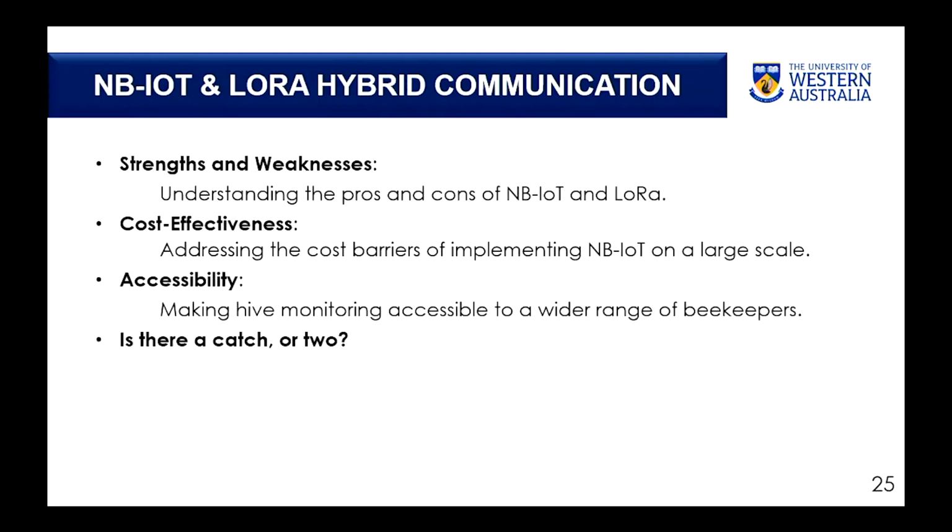So, trying to conclude, one more thing that we have done is we have developed a system where our communication is based on a hybrid of LoRa and NB-IoT. So our system can use both. But with LoRa, what is the problem? If you want to use LoRaWAN, you need a LoRaWAN gateway. If you go 400 kilometers out there in the jungle, do you have a LoRaWAN gateway? You do not. So you cannot use LoRa.